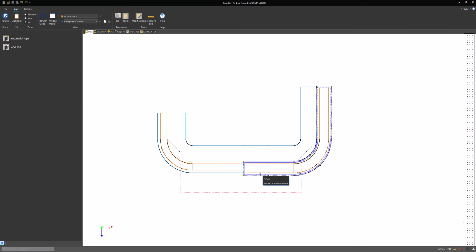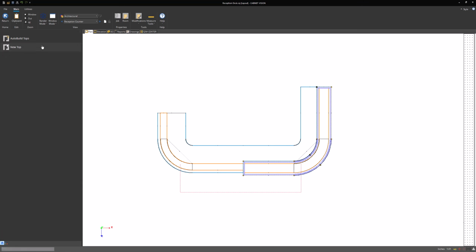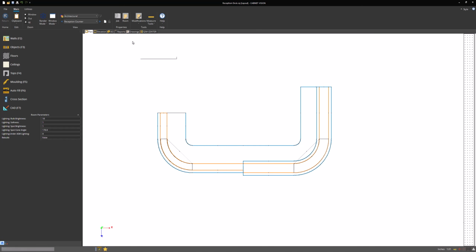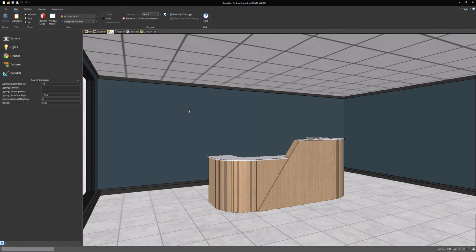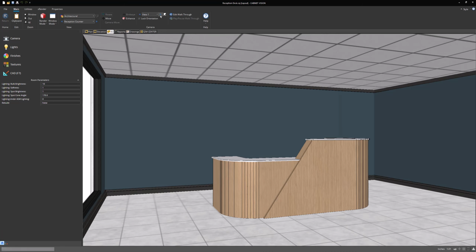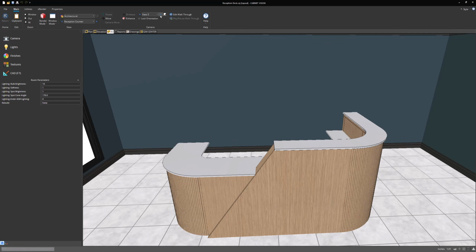And the last thing I'm going to do with this countertop is just set the height of it, because obviously this one's a slightly different height to the other countertops. And if we go into 3D now and take a look, we should see we've got a countertop up at the top here, and I'll just cycle around some of the different views. There we go. So we've got a countertop that runs around here and a countertop underneath, and obviously this nice angled section at the front.